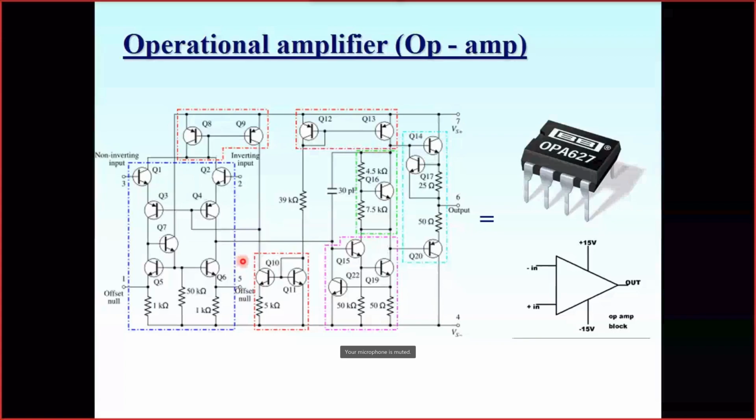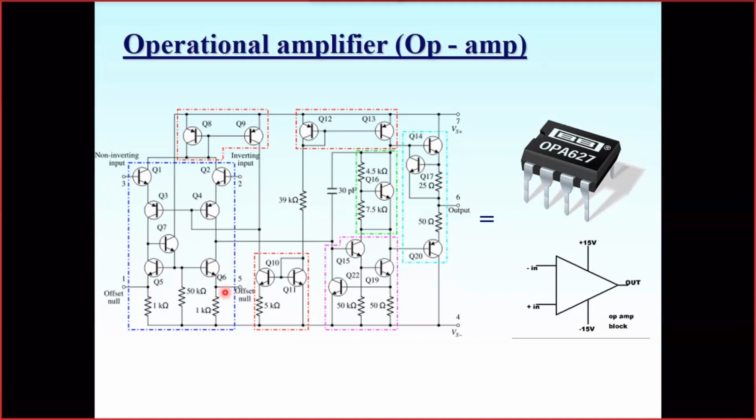That's why sometimes, if we need a very accurate 0 at the output of the amplifier when the inputs are equal, we wish to have an absolutely ideal zero at the output. We may slightly adjust the conductivity of these two left and right paths by shifting the symmetry a little bit between these two lines, inverting and non-inverting.